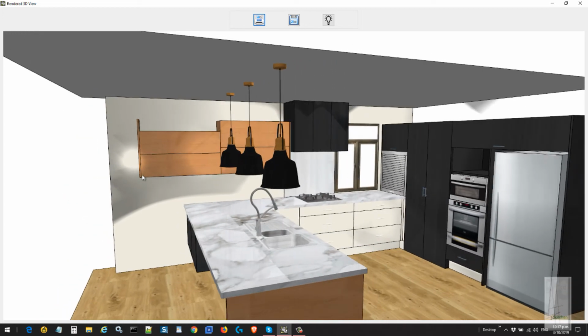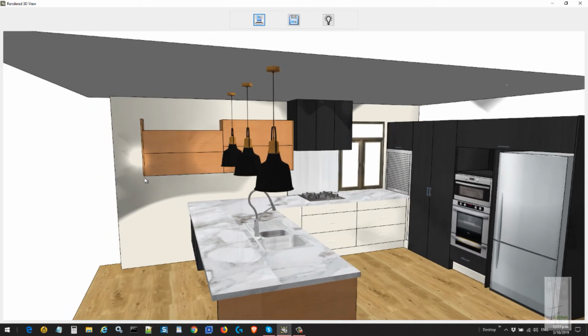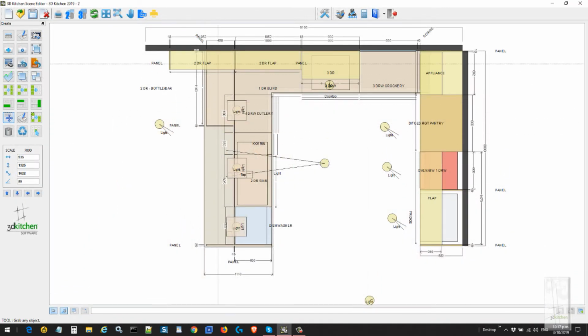So those properties are quickly changed. We can change the angle of an object as well. So I'm just going to pick this object up by holding the control key down. Clicking on the object just takes a copy of it and I'll place it here. So we can change the angle by holding the Alt key down on the keyboard, click the left mouse button and it will move around 45 degrees. The right mouse button will move it in the clockwise direction at 90 degrees.